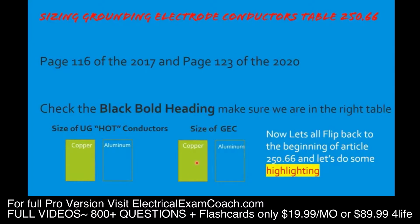And depending on what code book you're in, for this one, we have to flip back a page or two. Okay? We have to flip over to 250.52. I want you to flip a couple pages back to 250.52. And it's in part A, and it's part 4. And you'll see the black bold heading that says ground ring. At the bottom of that paragraph, I want you to highlight the 2 AWG, because that's the minimum size it's allowed to be.